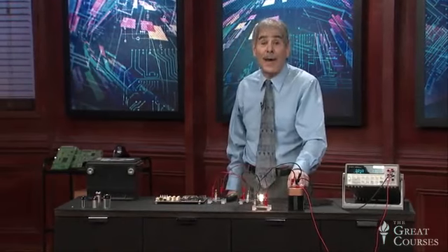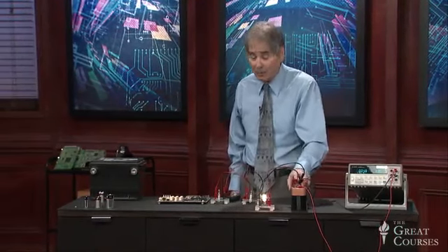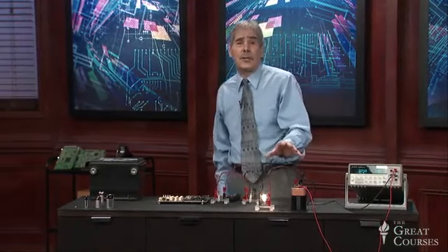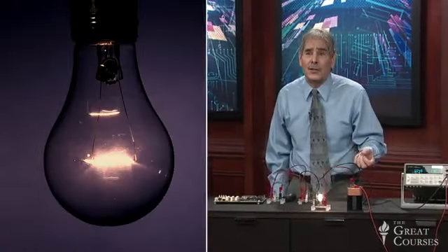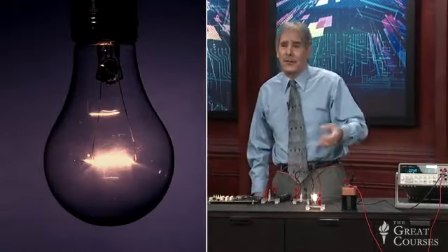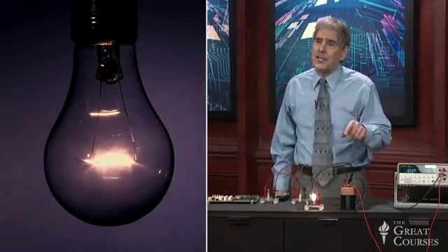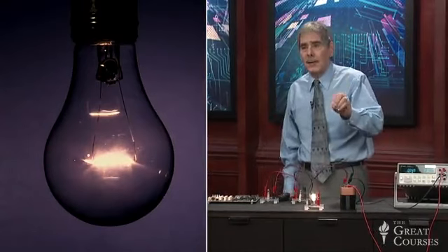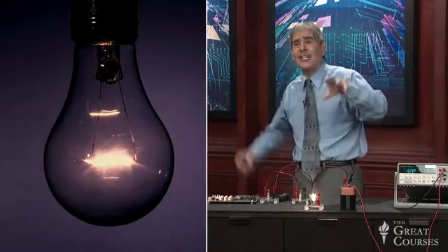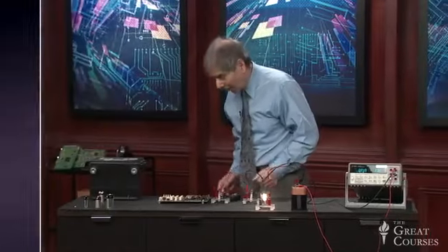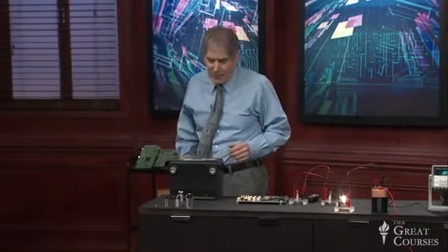Now this is an old battery. If I had a brand new fresh battery, it'd probably be okay. You may have noticed a similar phenomenon when the furnace comes on in your house, or the oven cycles on or something, and the lights dim. And what you're seeing there is the same effect, but caused by extra current flowing through the internal resistance of the household wiring.